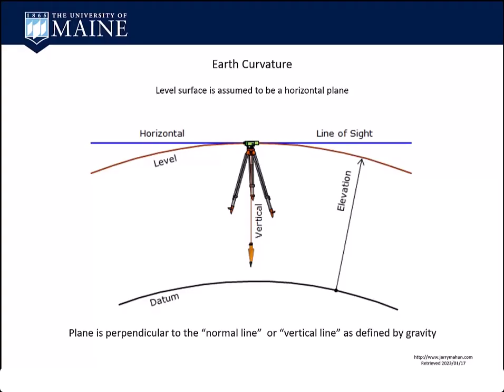So the effect of gravity is the same across the Earth. So if you have light or any kind of emitted ray like that, it's gonna bend down parallel to the Earth, because gravity is the same here, 100 feet away, 1,000 feet away. So it's always going to be below the horizontal line of sight of a properly adjusted level. If the level's out of adjustment, anything's possible. It's garbage.